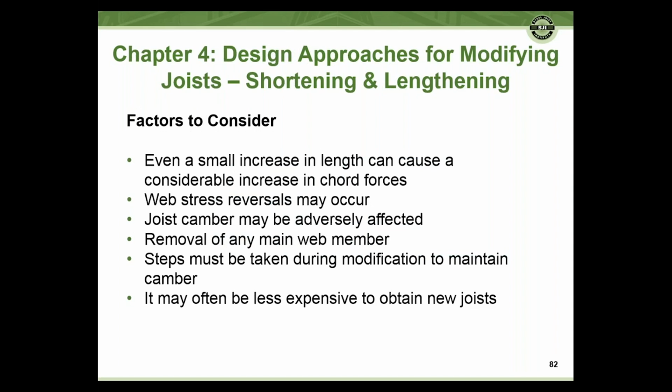So we've designed our two members, our end web and our end tension member, our end rod. They're both designed. Of course, you can use the same approach for designing the top chord. If you have to do an analysis or design of reinforcing the top chord, the same approach can be used. Just watch your unbraced lengths and make sure you're using the right unbraced lengths for the different members.